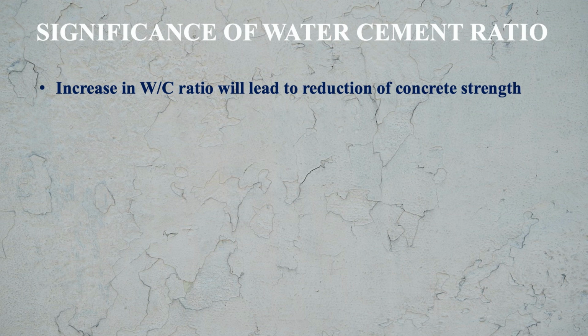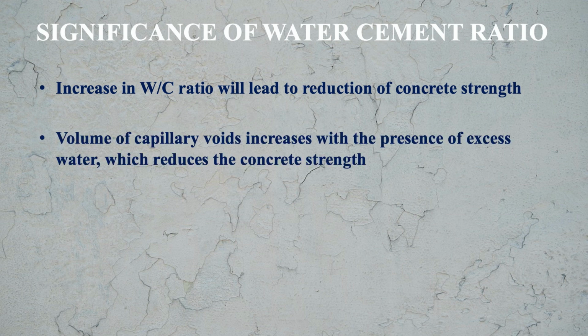Increase in water cement ratio will lead to reduction of concrete strength. Volume of capillary voids increases with the presence of excess water, which reduces the strength of the concrete. So that way you see that water cement ratio is affecting both ways. If it is less, then also it is affecting the strength of concrete. If it is more, again it is affecting the concrete.